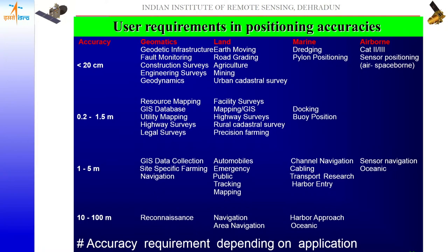Because our Indian plate is moving, and when you are going to Badrinath or Kedarnath, in that region your velocity is getting modulated. There is not only Indian plate movement, but there is a Eurasian plate movement also. One plate is going down, another plate is going up. Due to that your velocity is getting modulated. So when we estimate the velocity with respect to India fix, we see that it comes to approximately 18 millimeter, 15 millimeter with respect to the Indian plate.